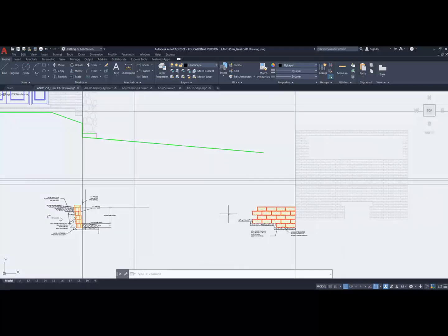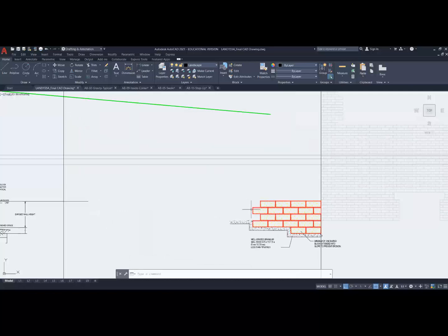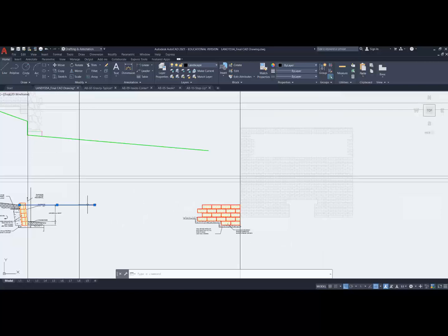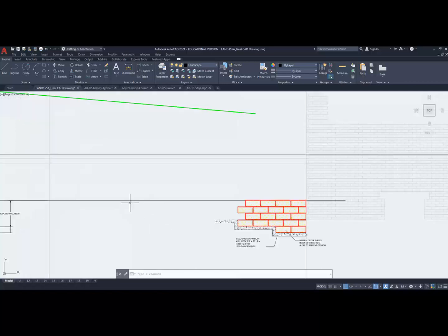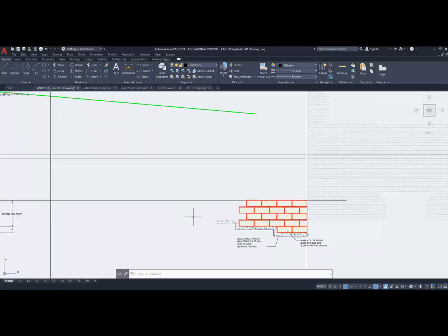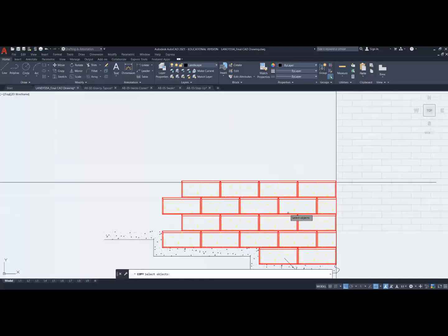And you can see I'm going to get very close to getting this to a very short retaining wall very soon. That's the height of grade that's behind all this. That's where grade is back here. So that's the height I need to maintain. Here's where I can make a design decision and say, I want to have 2 layers of block or 1 layer of block or 3 layers of block visible for the remainder of this. And that's okay to do. That's not a problem. So I'll have a very soft, gentle slope through here. And by doing that, it's very easy to make those types of decisions and carry them through. So that's what I'm going to do.